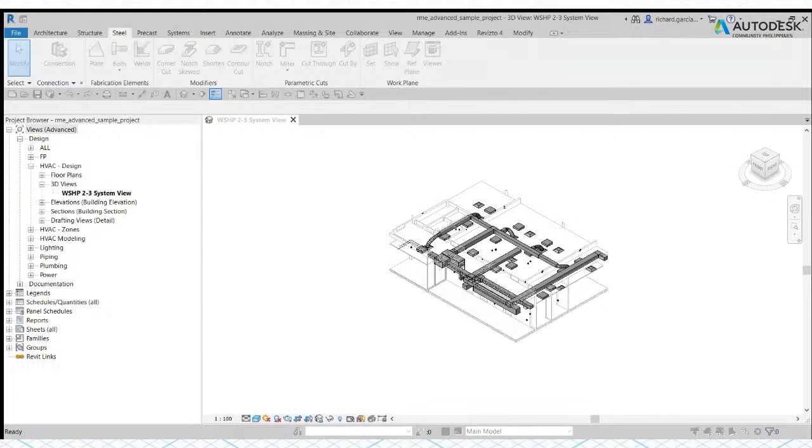And then the first time you open your project after installing Revit in your machine, you will notice the selection here and pre-selection. They are both bluish color. Okay, so they are both on the blue color. Okay, so that's why I change it. So what I want to do is every time I select the object or the element, I want that to be turned to red and semi-transparent, and then the pre-selection will turn to green. Okay, so this is my preferred settings. So let me just quickly show you. I will select here OK.